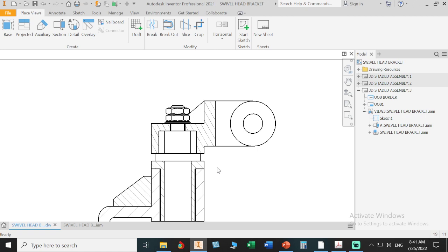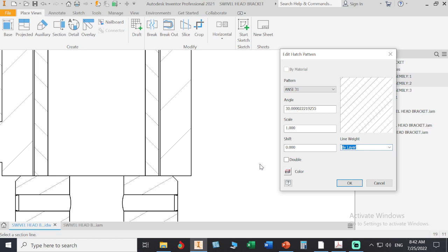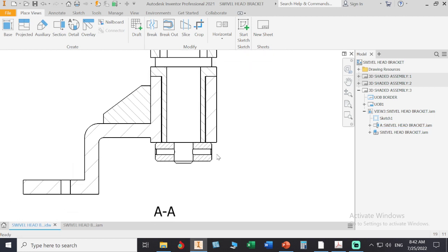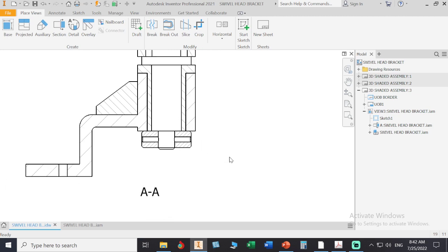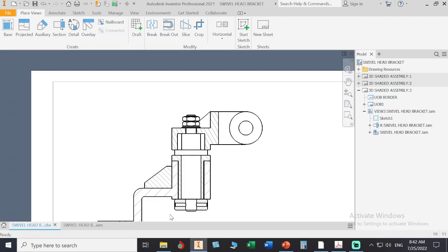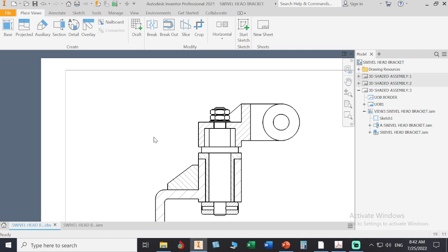Now we go here, and this one has to be the opposite of that one, so this will be 45. It's a small part, let's give it 0.5. Okay, here, okay. Can you see the pin is inside? It's a standard part, so it's out of section. Okay, my head, give it 45, I see. Yep. 45, and keep it as 1. Hit okay. Save.